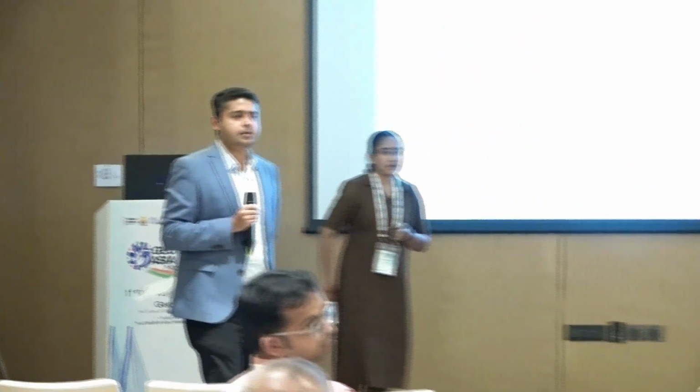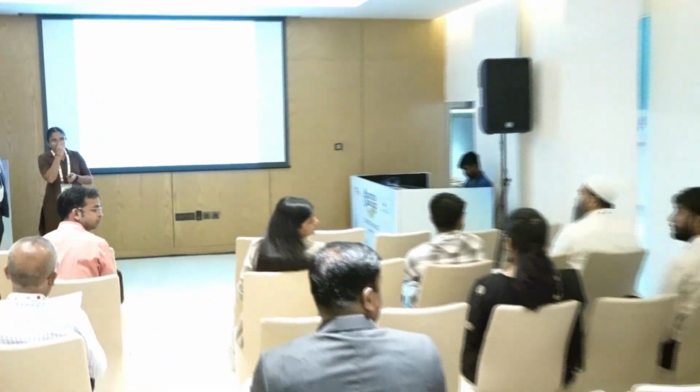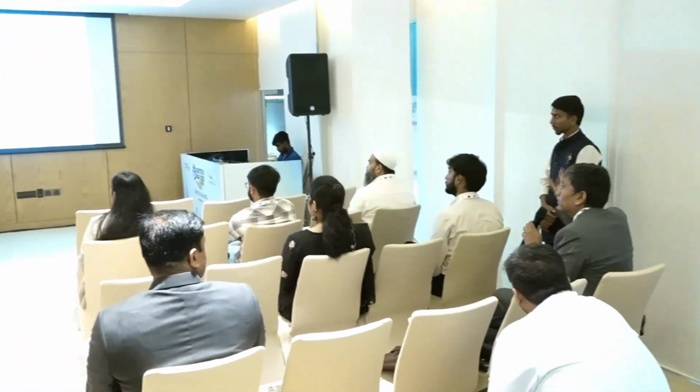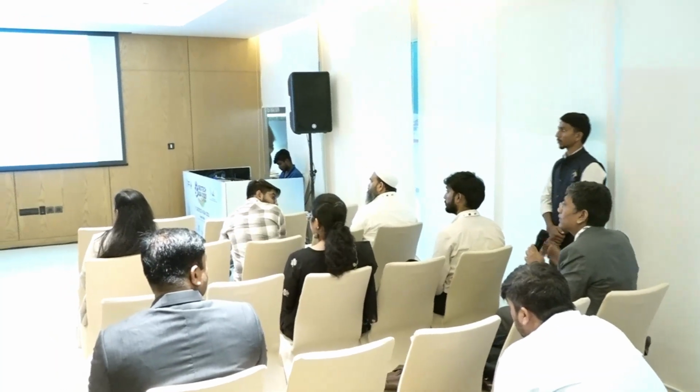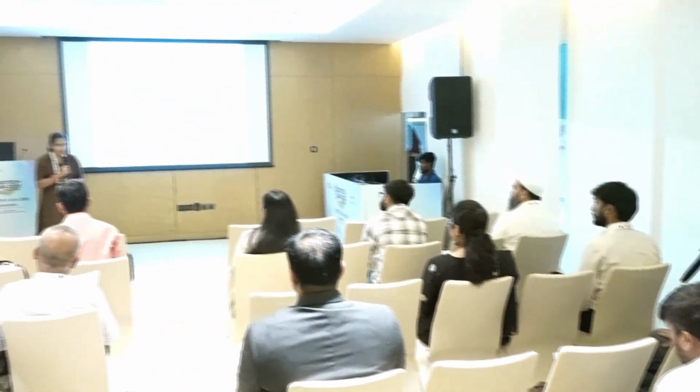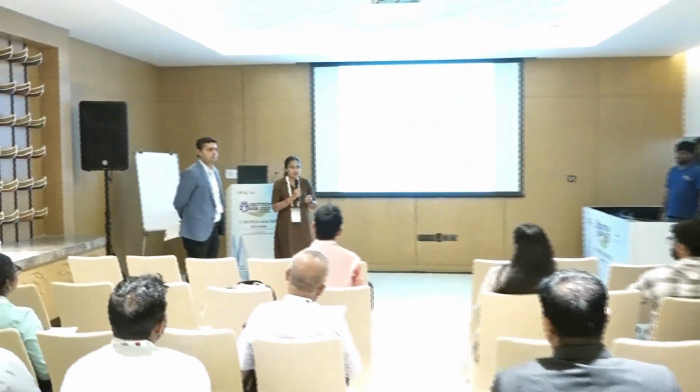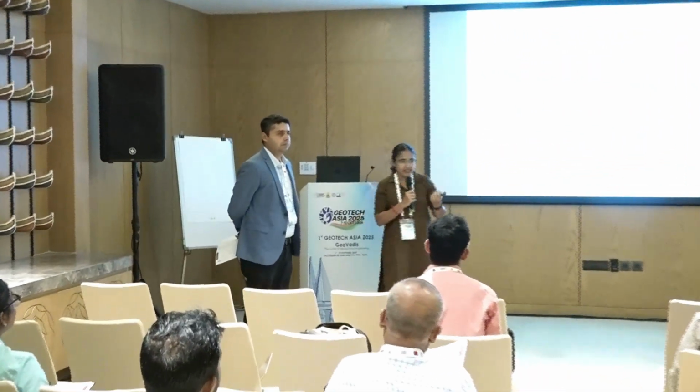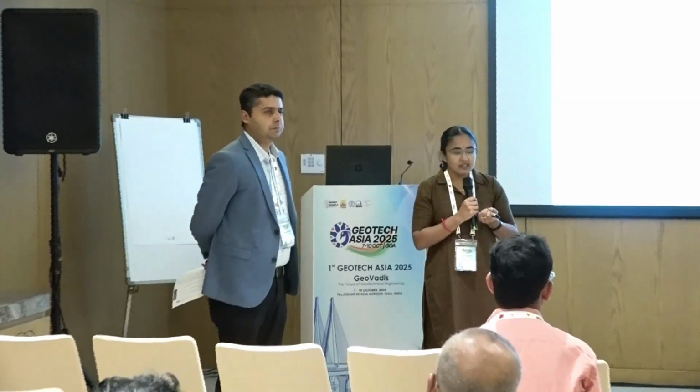How is the cost comparative analysis of xanthan versus using bentonite? What will be the economical solution? Economical one is bentonite, sir, because we usually get food grade xanthan gum biopolymer, so that is costly. Bentonite is much cheaper. Industry grade bentonite will be much cheaper.